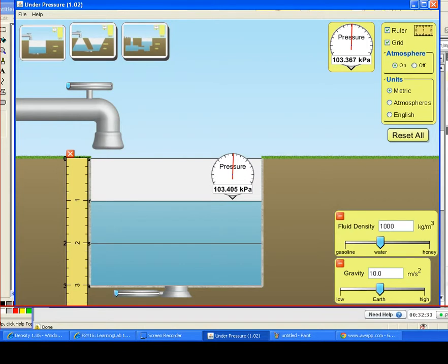I assume you know. So you start with 103.418. You're taking away 1 meter of air, and that corresponds to pressure of 0.012 kilopascals. You're adding 1 meter of water. That corresponds to pressure of 10 kilopascals. So 103.418 plus 10 minus 0.012, and that should give you 113.406. Let's measure it. Let's see whether that's what we get. So down here. Yes, so with experimental error we agree we are getting the value that we expect.